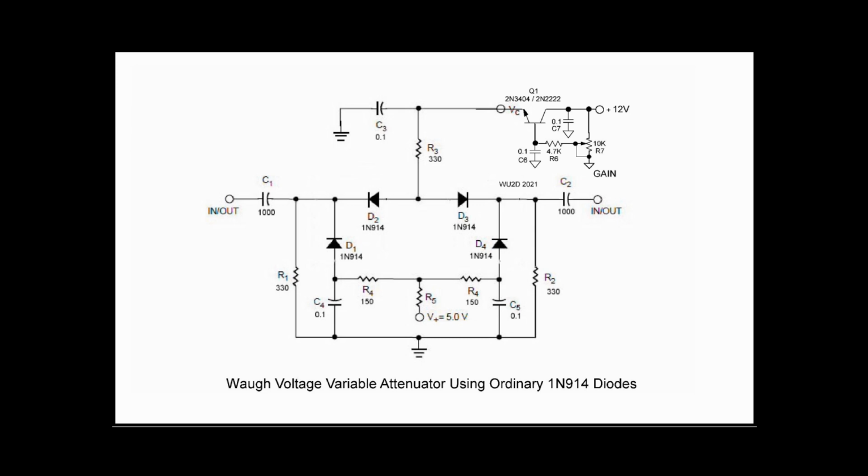So the twin diodes which occupy the position of the series resistor are physically set up to be 180 degrees out of phase, resulting in cancellation of even order distortion products. The resulting attenuator network is symmetrical, and the bias network is substantially simplified. You do need enough reverse bias to turn the diodes completely off, and you have a 5-volt standing bias that keeps the diodes on. So you need to overcome that.